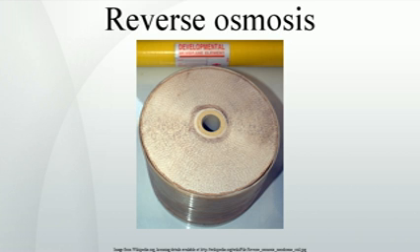The membranes used for reverse osmosis have a dense layer in the polymer matrix, either the skin of an asymmetric membrane or an interfacially polymerized layer within a thin film composite membrane, where the separation occurs. In most cases, the membrane is designed to allow only water to pass through this dense layer, while preventing the passage of solutes, such as salt ions.